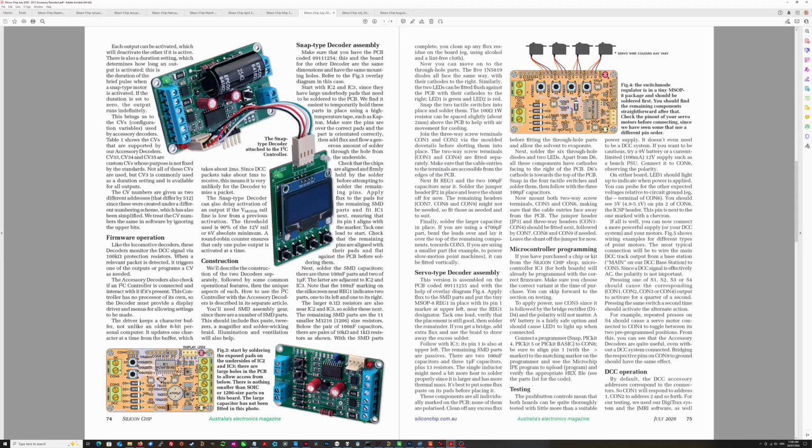And this is about to get to this. This can be used to control and program the decoder. With the regular decoder, you can just put the train on the programming track and program it. But this board is stationary, it's fixed in the layout, you can't really do that. So we have this small extra board that can plug into it that can do things like change its address and also just switch the outputs on and off. In fact, you don't even need a DCC system to use this. You could just permanently attach this controller and just use the buttons and screen to control it.